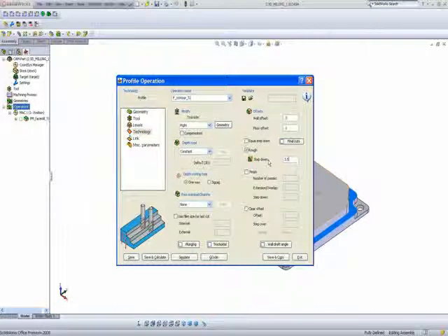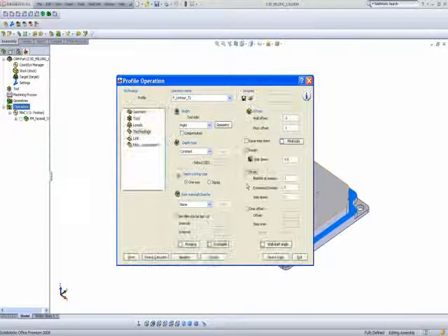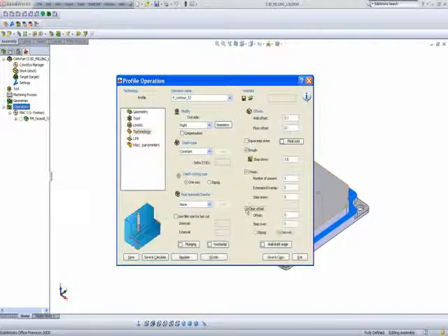And with this particular tool, I can also do a finish cut. So I'll be choosing also to do finish. And I'll be doing it with one pass. And my step down, I can leave this at 0 since I'll be doing it all in one step down for my finish cut. Now we also have something here called clear offset. In my clear offset, I can actually start further away from my wall and then work my way in.